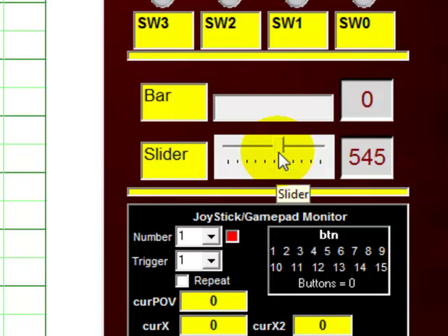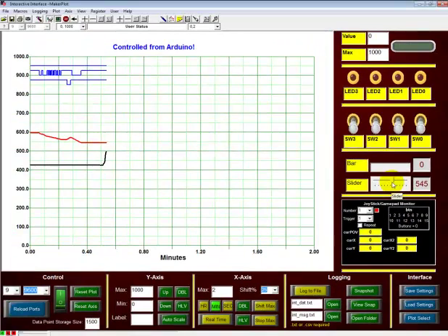So let's do a couple of tests with our potentiometer. We'll move our potentiometer through the set point, take a snap, and as you'll notice, our set point digital line went from 0 to 1. Going below the set point, it goes from 1 to 0. Going above the set point, we took another snap.